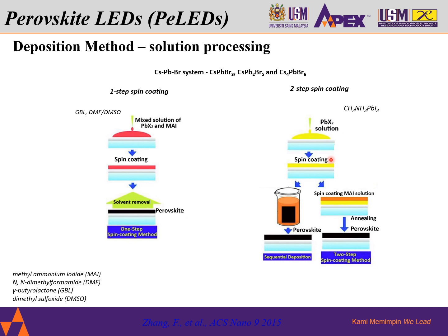First, it was spin coated with a PbBr2 solution, which is a mixture of PbBr2 precursor with DMF solvent. After annealing the first layer for a few minutes, the CsBr dissolved in methanol was spin coated to form the result of inorganic perovskite CsPbBr3. This method was basically developed to improve the control of the perovskite crystal formation and also the growth.